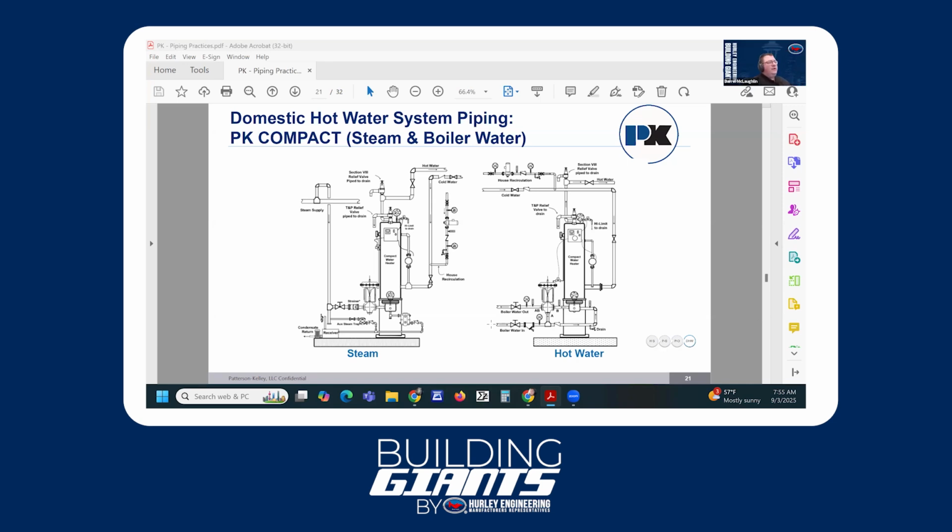No, that's true. So the gasketed plate or raised plate, it's a real concern. If you run too high, it's time, temperature, and turbulence. And if you don't have those just right, you can foul them up or scale them up fairly easily on the potable side, where you have minerals and salts and things like that that will precipitate. So that's a concern for the amount of flow you have.